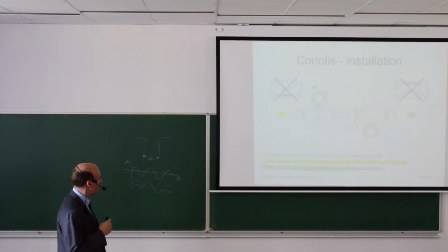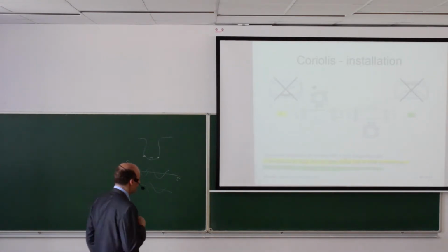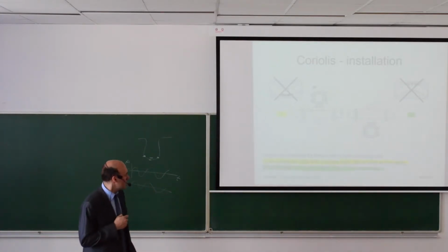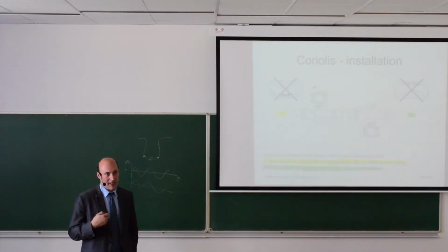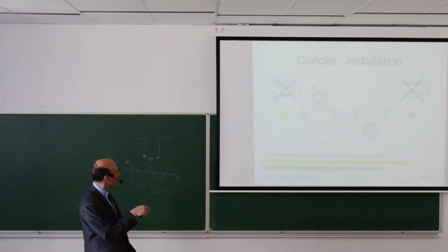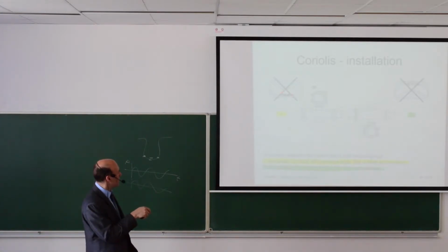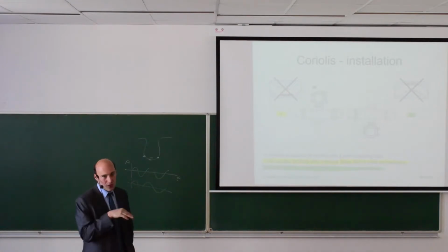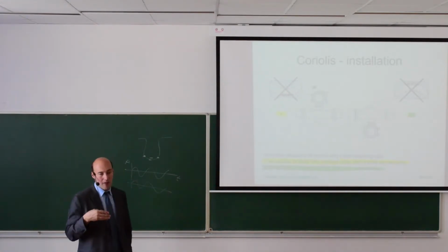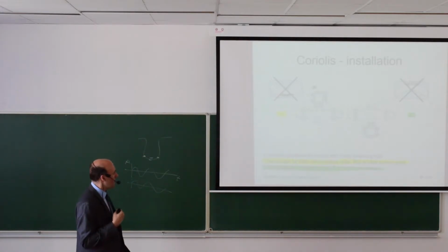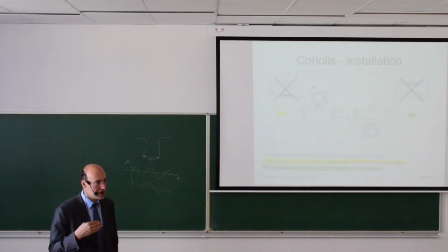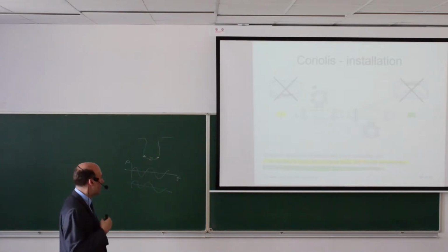You see, this is an example of a horizontal installation, and this is not suitable for liquids with solids inside. So if you have this example, then this is not an ideal position, because the solids will accumulate at the bottom position, and they can remain in this position. So the horizontal installation is only for clean liquids that do not have any solids in them.